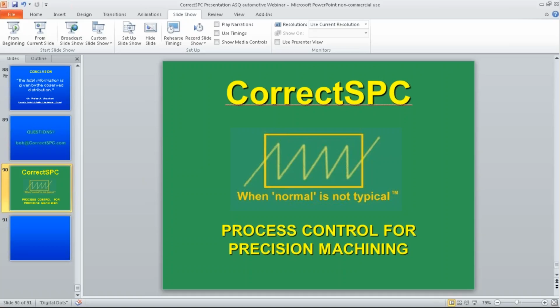Oh, it will flatten. But what I'm afraid of is, first of all, most of the auto compensation isn't looking at the high and low, right? It's only going to be looking at one diameter. So its decisions may be overcompensating just based on the measurement error. I don't know. And then it's going to make an adjustment even though you're not at a control limit, right? It's just going to constantly try to run to the mean. So all of these things just mean that it becomes the source of variation on top of the tool wear, which is always there. And the idea is to pull away all the variation so that only the tool wear is there, and you only make adjustments when you need to.